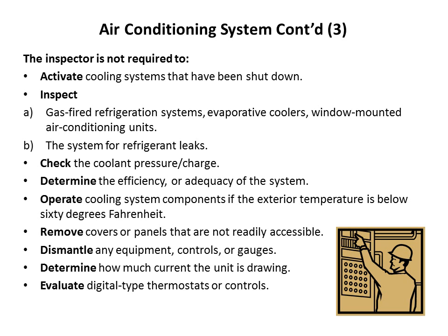Remove covers or panels that are not readily accessible, dismantle any equipment, controls, or gauges, determine how much current the unit is drawing, and evaluate digital type thermostats or control.